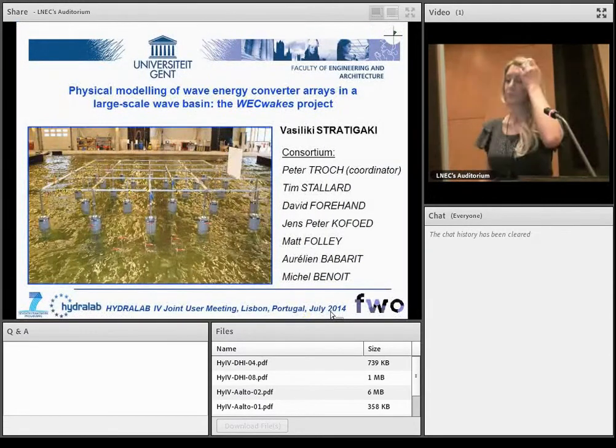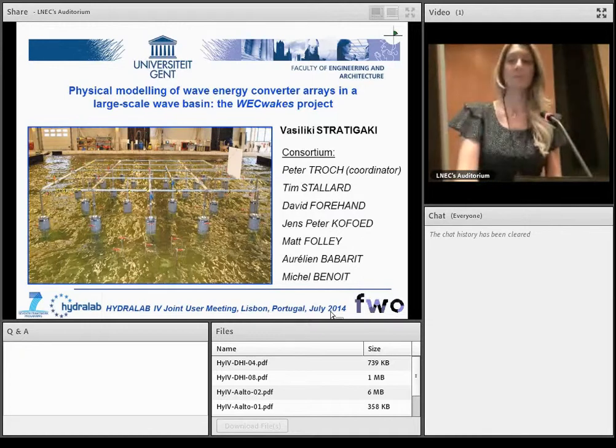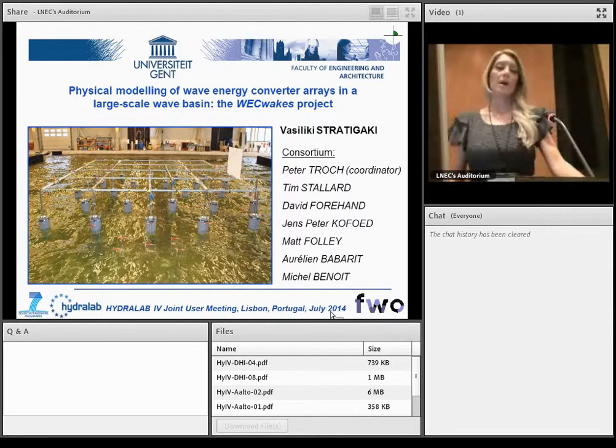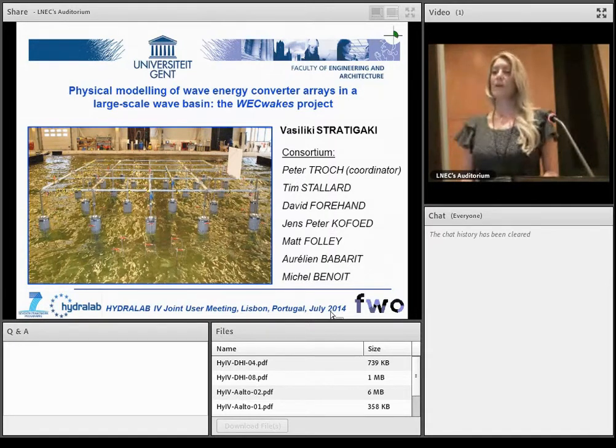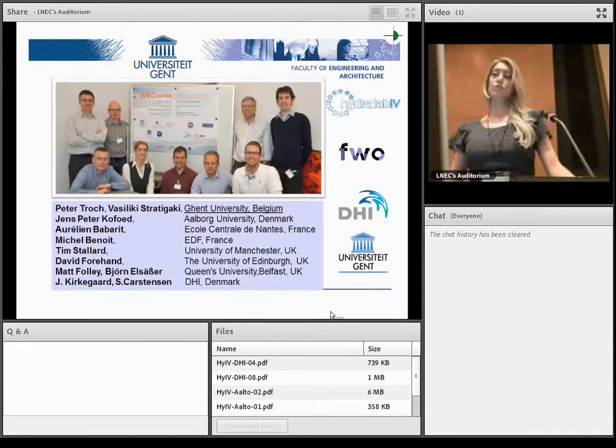Wave energy converters, abbreviated as WECs, are devices that capture energy from waves and convert it into electricity. There are a lot of different concepts, but mainly two types of devices. Those based on the oscillating principle, like the Pelamis, and those based on the overtopping principle, like the Wave Dragon. But what they all have in common is that they have to be installed in large numbers, forming large farms or arrays, and covering large surface areas in order to produce sufficient power.